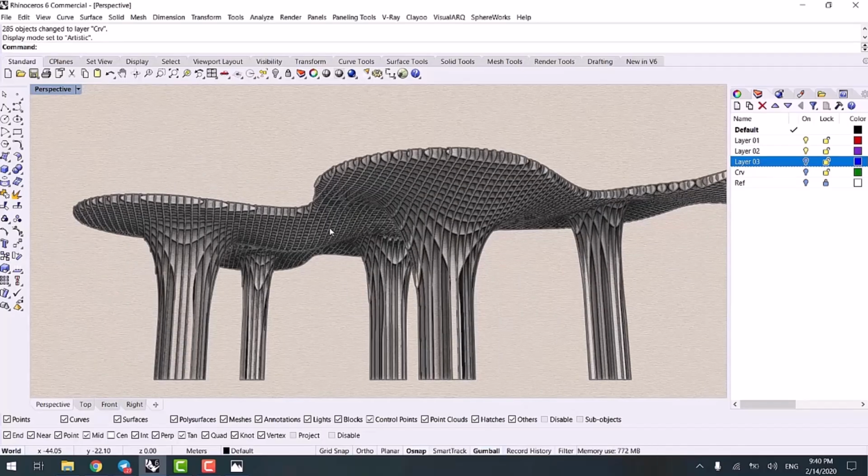Therefore, we could put the things we've done so far into some simple commands. We created the work's plan, then we changed it into a layer. We could have changed the layer by playing with the control points up and down, or other commands like soft edit surface and soft move. And then with trim, we carved the place of columns. And then with the help of blend surface, we connected the columns. And in the end, contour and extrude.